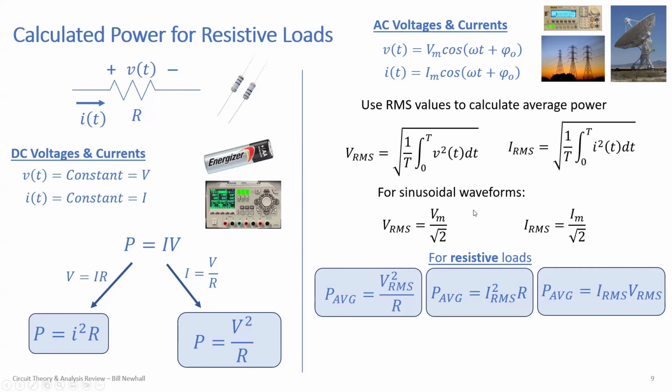If you have an antenna, I like to use antennas as examples because they're not a component, but they behave like resistors. If you measured voltage and measured current, they would be proportional, and if they're sinusoids, they would be in phase for a well-designed antenna.